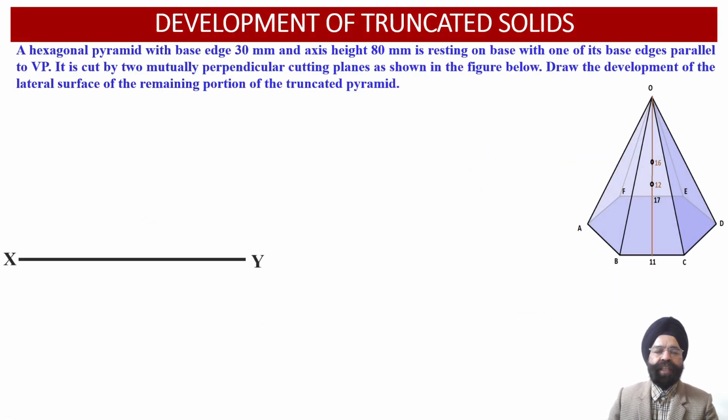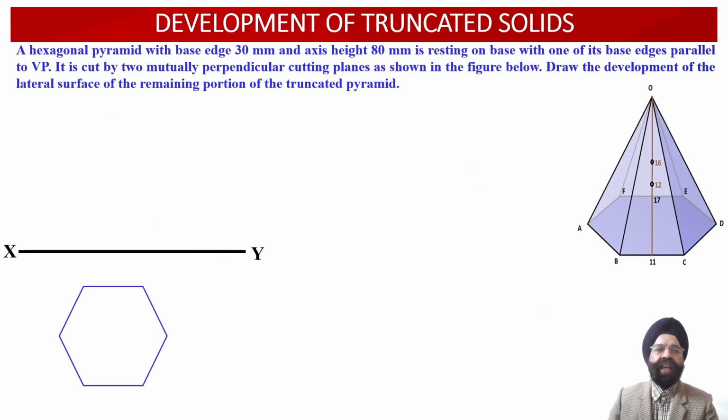Let us now proceed with evaluation of top view projections and the front view projections of this hexagonal pyramid. Now as the observer is going to view this hexagonal pyramid from the top, we are going to obtain the hexagonal projections onto the horizontal plane over here in the top view projection. Now we can check, we have obtained the hexagonal projections onto the horizontal plane with an edge length of 30 mm. Now the 6 points of the base we have drawn A, B, C, D, E, F, and here we can check that this base edge EF happens to be parallel to the vertical plane.